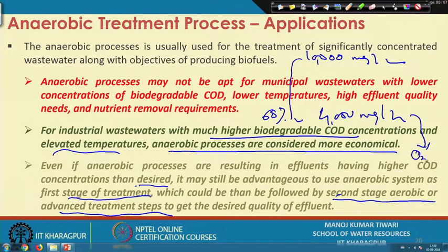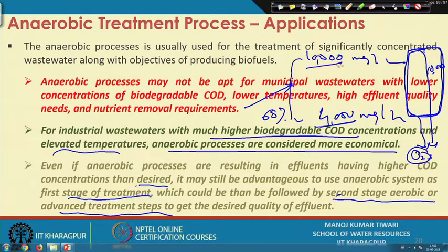So, your oxygen requirement now, or the requirement of aeration, would correspond to just 4,000 milligram per liter substrate concentration, but if you directly use the aerobic process, your oxygen requirement is too high because that will correspond to 10,000 milligram per liter substrate. So, the amount of oxygen or aeration you save here is worth adding an anaerobic step, because you are not providing any energy to this one and you are getting removal of 6,000 milligram per liter even at very moderate efficiency without too much investment.